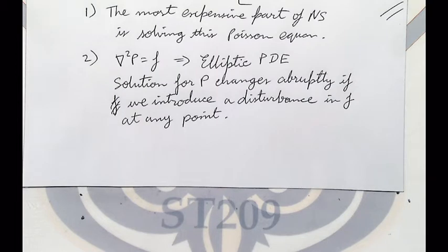No. So, imagine the surface of a lake, okay? And it's calm and smooth, and you drop a tennis ball at one end. The assumption of incompressible flow says that the pressure change will be instantaneous throughout the lake. Every point, if somebody's measuring on the other side of the lake, they will see an instantaneous change in pressure because I've dropped the ball. The surface waves do not need to go there. That's what it means physically.